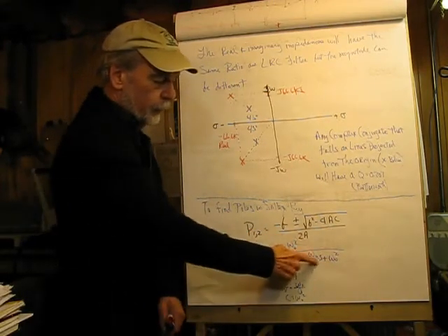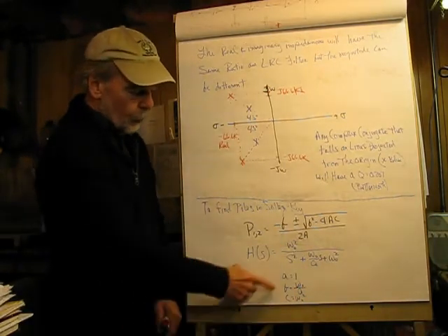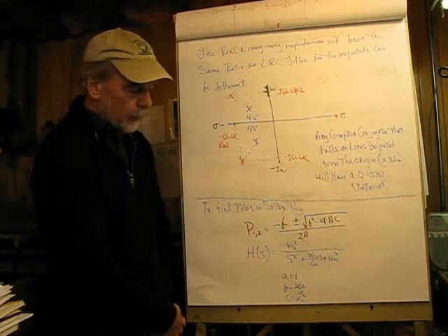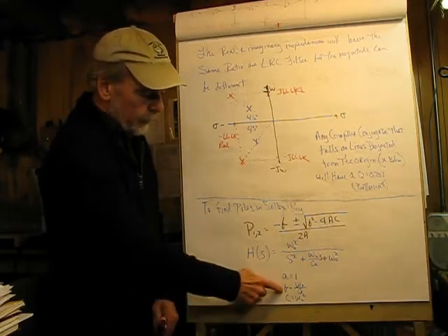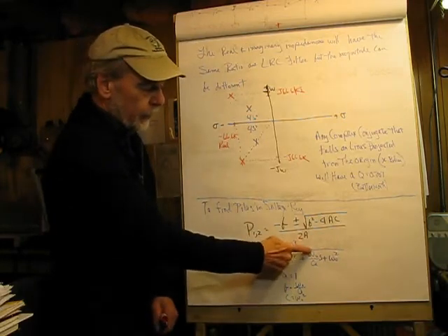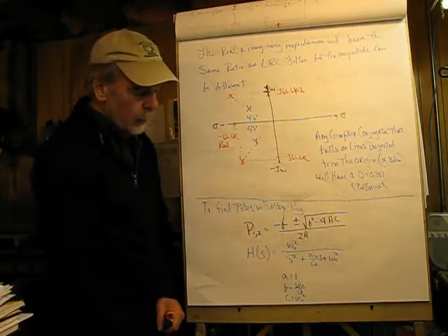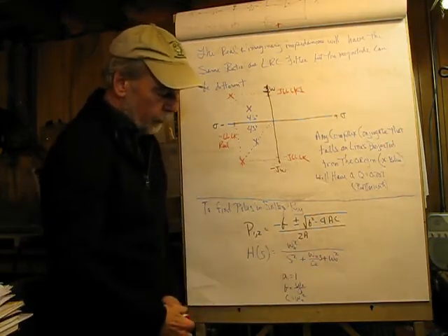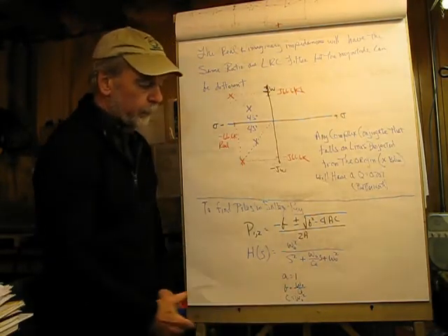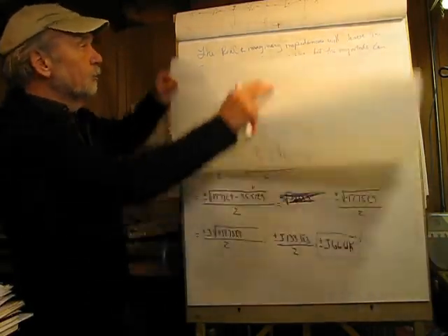I'm very interested in the second order equation in the denominator. So in this, I'm going to let a equal 1, and b is going to be equal to omega 0 over Q. That's this guy. And a being 1 is the coefficient of s squared. And finally, c is going to be omega 0 squared. So once I have that, not too hard to follow.